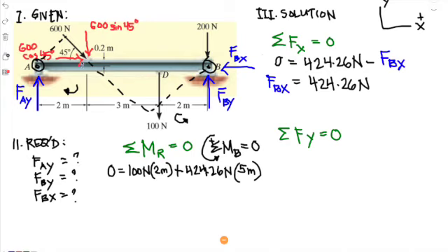So notice here, the 600 newton force is applied at this point of the beam. And we have a dimension here given as 0.2 meters. So it means that we have a perpendicular distance here between point B and the x component of 600 newtons. It means it doesn't intersect B. It means it will have a tendency to rotate B, or a moment at B. And that tendency to rotate will rotate it clockwise.